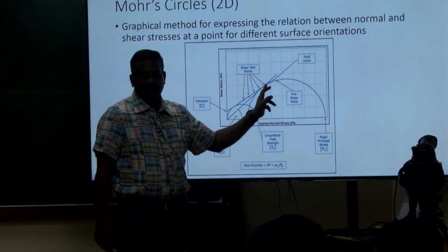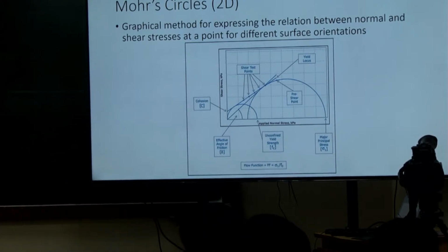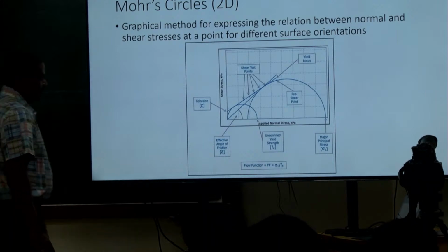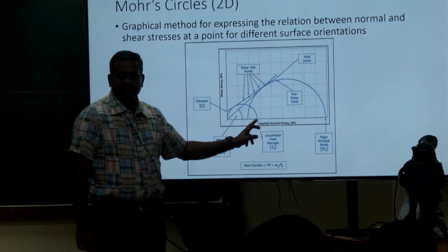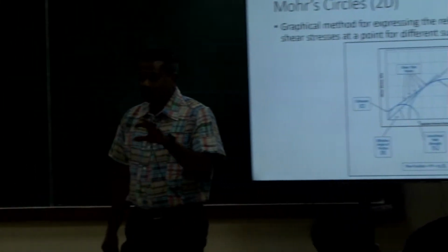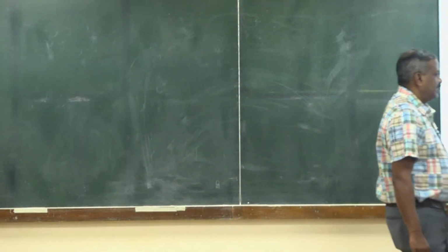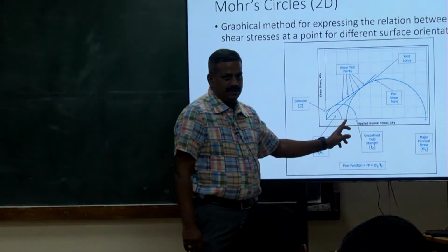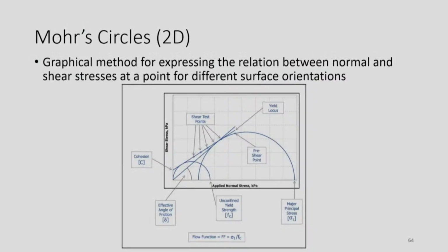So touching the last shearing point, you draw another circle, that's the major Mohr circle. So you draw 2 circles and then you get the other values such as unconfined yield strength. This will be the unconfined yield strength, the right hand side of the minor Mohr circle. You get the major principal stress that's acting on the powder at that shearing point or for that yield locus, and also you get the minor principal stresses. Hopefully I have one more picture that will explain this major and minor principal stresses in a minute.